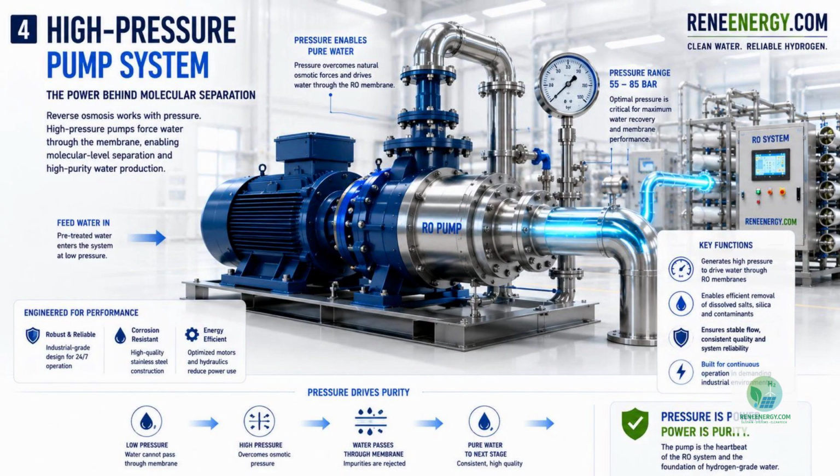This pump is the heartbeat of reverse osmosis. RO does not work unless pressure is applied. Natural osmosis wants water to move in one direction, but reverse osmosis forces it in the opposite direction by applying pressure. In industrial systems, this pressure may reach tens of bar depending on water quality and system design. The pump must provide stable flow, reliable pressure, and continuous operation. If pressure is too low, separation becomes weak and water quality suffers. If pressure is too high, energy consumption increases and membranes may experience stress.